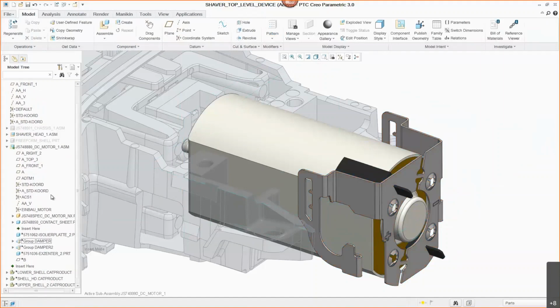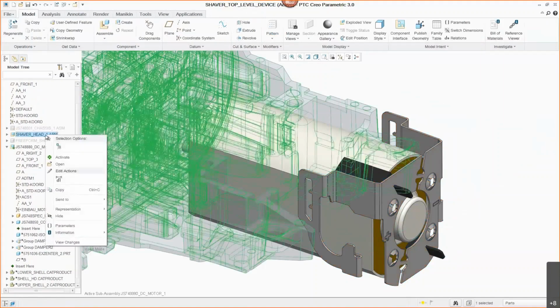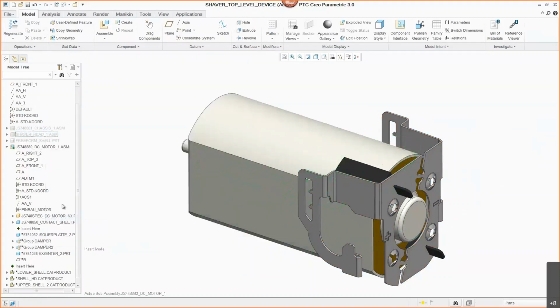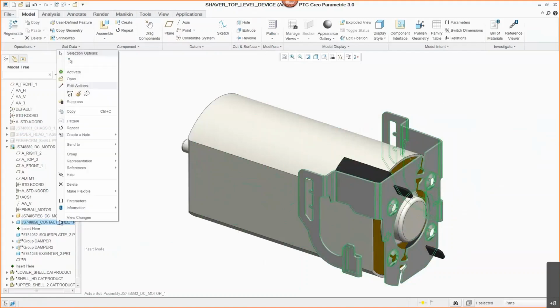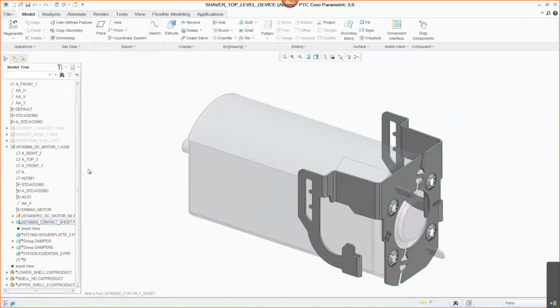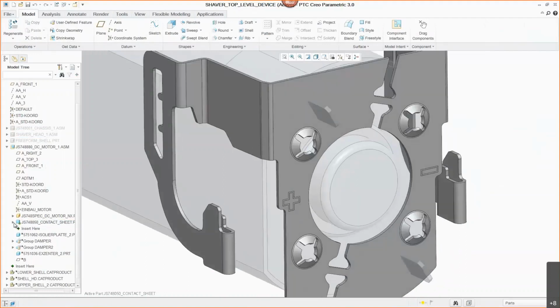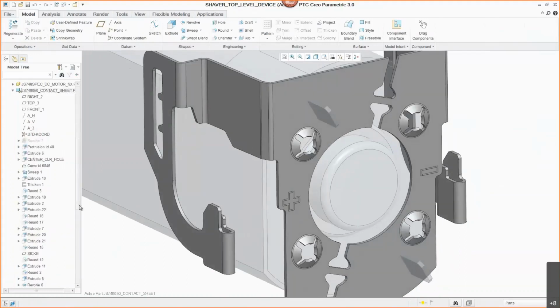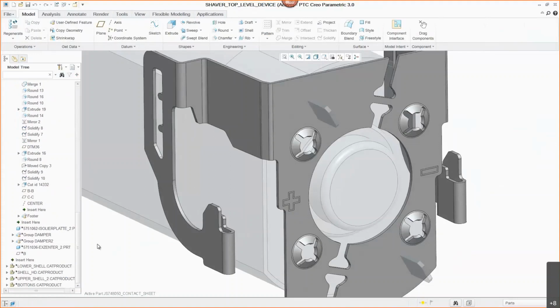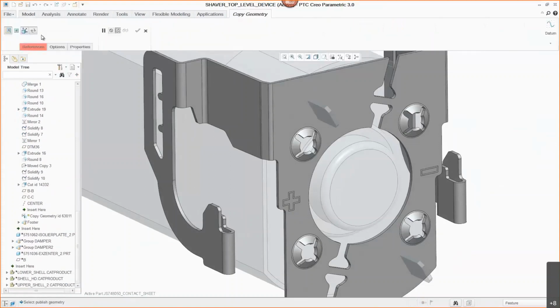And so what you have here is your sheet metal casing that you put on it, but you wanted to wait for the motor to see where those tabs are. And as we can see, those tabs need to cut through this sheet metal. So that's not a problem. We can make edits to the Creo geometry referencing the part that's opened as an NX part. So we can design around it and integrate it into our assembly completely.